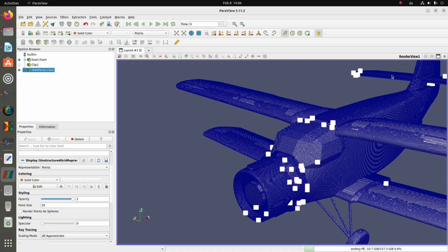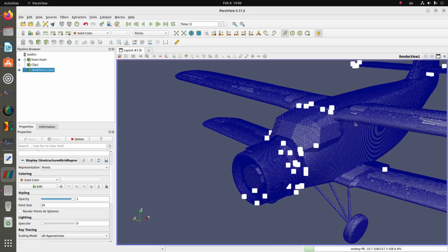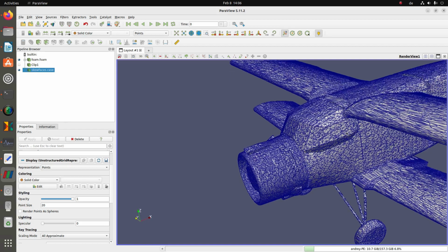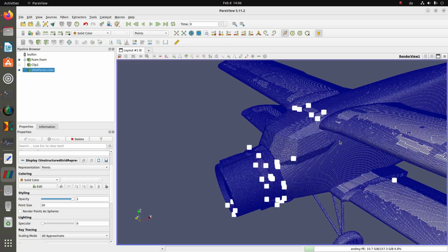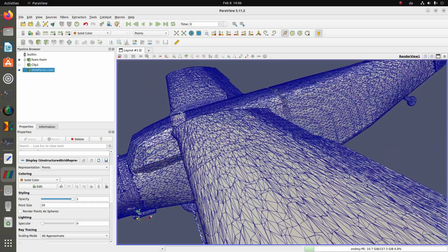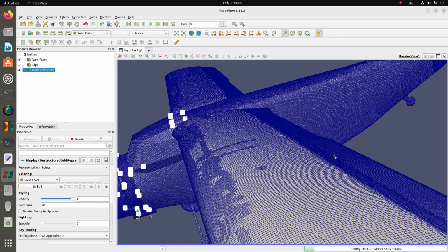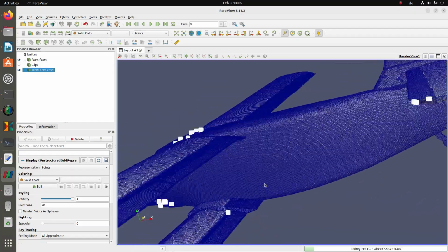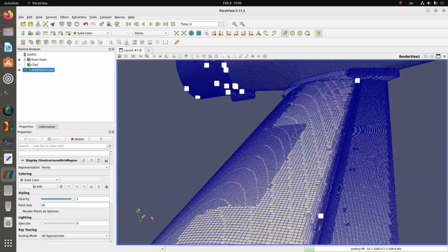Another task for us is to check the geometry. I look at all the critical points where the meshing problems could be. For example, we have to look at all places with small distance between two surfaces. These places are where the gap is. There are such places on flaps and wings, for example, on wings bottom.